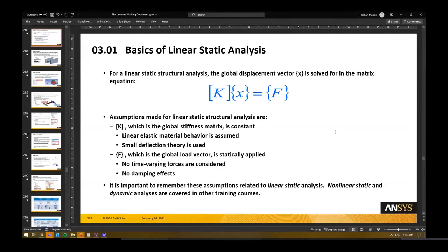What we're trying to solve, we've got this stiffness matrix K, we've got displacements X, and we've applied some sort of force, and we're looking to solve the actual displacements on the nodes. And then from the nodes, we look at the integration points to determine the strains as well as the stresses, and that's what we can see on our actual system.